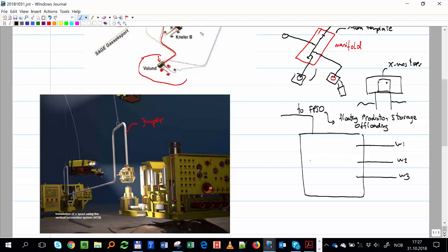But there inside you have a flow meter. You have one component that Norwegians trust, and they say you are allowed, but you have to test each well, and you're allowed to do it with a multi-phase meter. So you have to find a way to send the production from well 3 at will through the meter and through that line, or well 2 through that meter, through that line, and well 1 through that meter and through that line. You have to find a way.